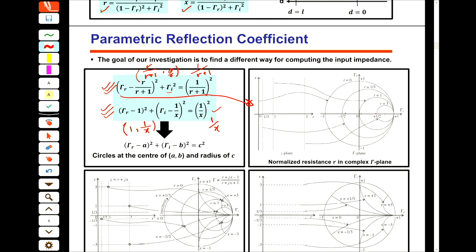So if I am looking at an impedance that has an R of 50 ohm, then R equals 1 if I normalize it to 50. Because I said that z in equals Z in divided by Z naught. So if I'm looking for an impedance where the real part of Z in is 50 ohm, then it is somewhere on this circle.